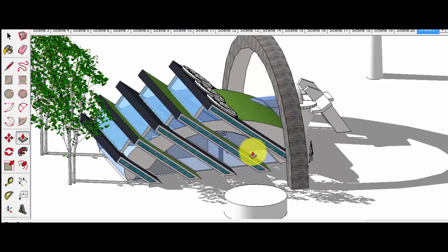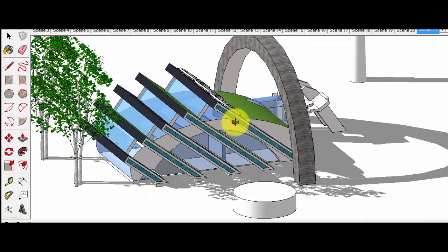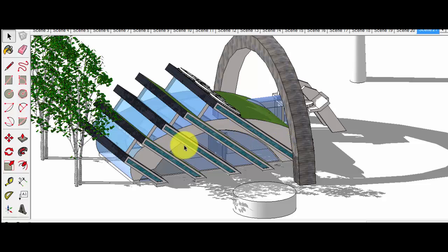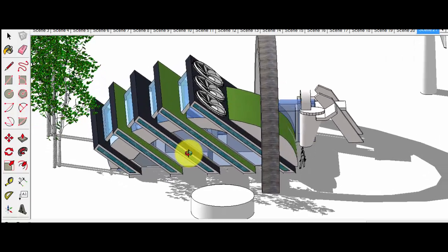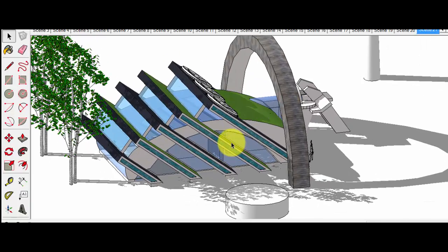Passive solar design requires building materials that are a good heat sink. A good heat sink meaning that the sun would be absorbed by the different building materials, in this instance concrete and steel, absorb that heat and releases it slowly during the day, heating up the building in winter, for instance. During summer, of course, we'll have the deciduous trees and these panels or screens which would screen the sun out. But let's continue with the winter scenario where we want to heat this building, where most energy is required.